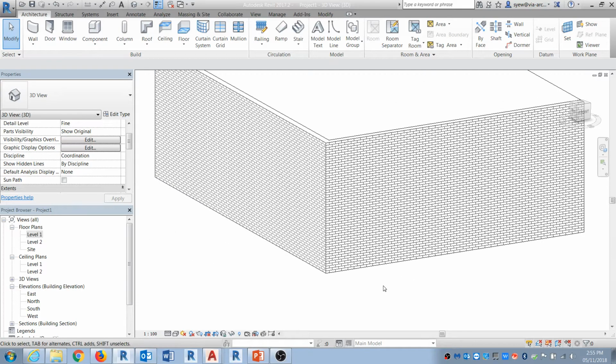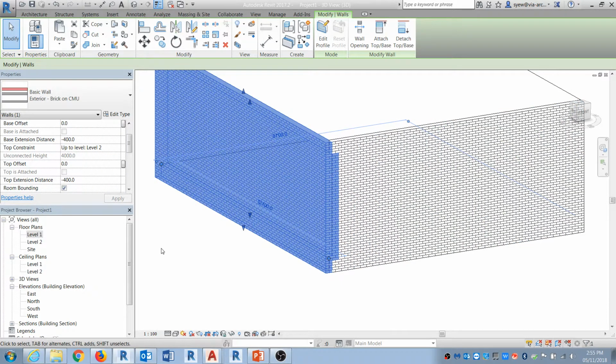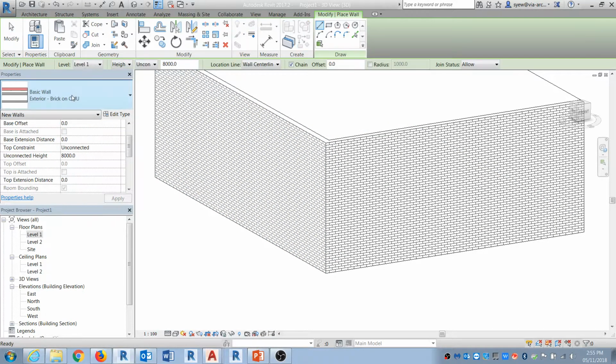All right. The next thing I'm going to talk about is, let's assume that you want to put two materials in this wall. By default, what a lot of users would recommend is, why do that when you can use stacked wall? Perfectly legitimate answers. The only problem with stacked walls is that you're going to have an issue when you try to tag those walls.